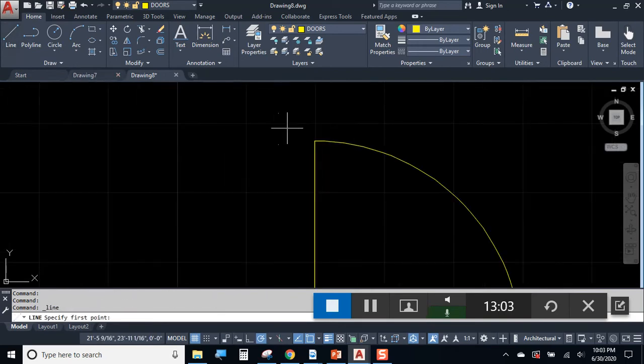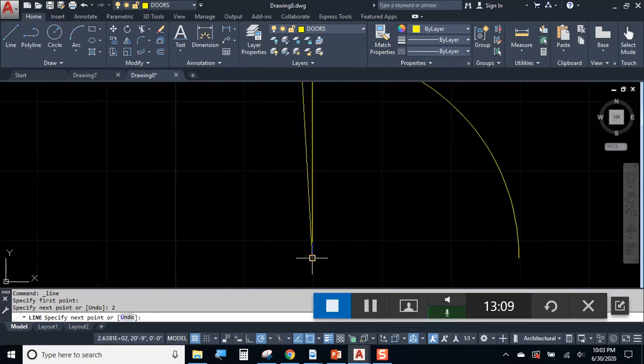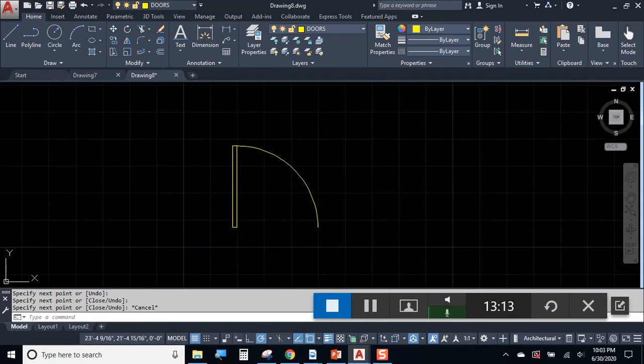If you want to get fancy, you don't have to have just a line. You can make your door panel thick. 1.5 inches, 2 inches, whatever makes you happy. Look at that, now I have a fancy door. Okay, my next step is going to be to group that geometry together, because when I select any part of it, I want to get everything. So make the group and then make sure the grouping button's turned on so it actually behaves like a group.